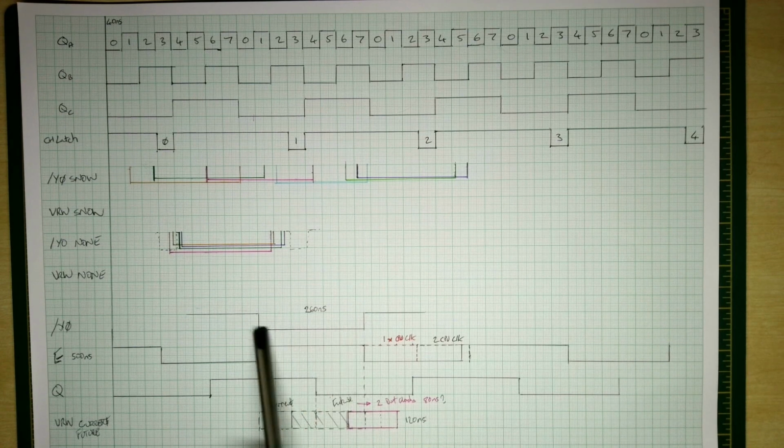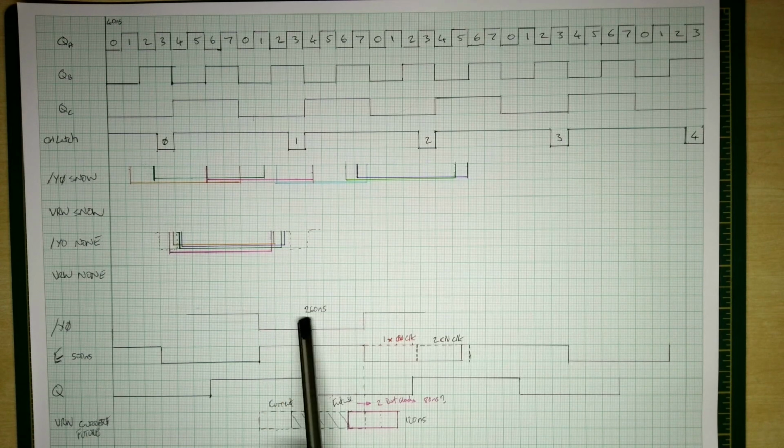When we had the 4 megahertz clock, it was close to about 500 nanoseconds wide. But now with the faster clock cycle, we can probably make this a little bit shorter. And certainly the video RAM that we're using has a 15 nanosecond access time, so the video RAM is certainly capable of working a lot faster.